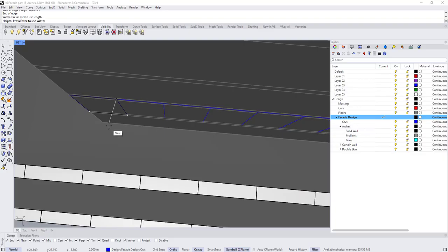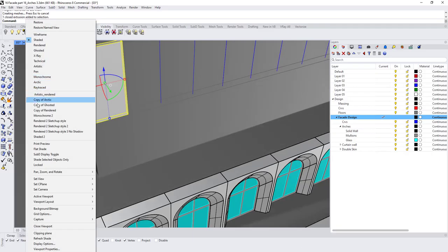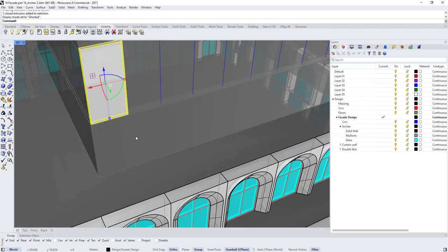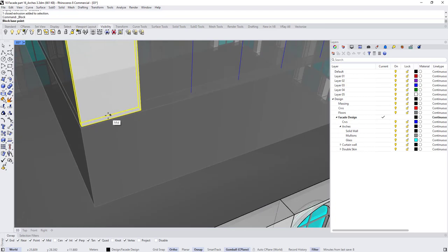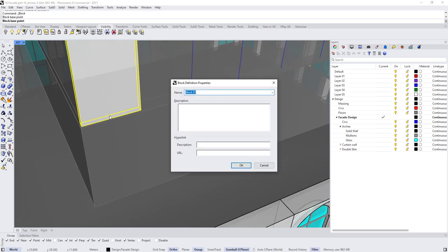Now let's create a 3-point box and choose the facade layer from here to here, and the depth is going to be just 0.2. Yeah, 0.2 is fine. Switch to the ghost mode. Select the box, choose define block, snap to the midpoint, and let's name it F2.